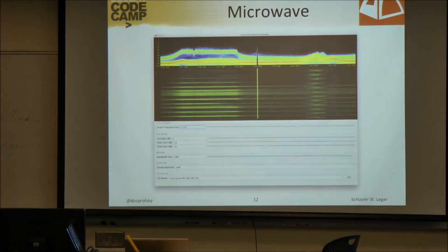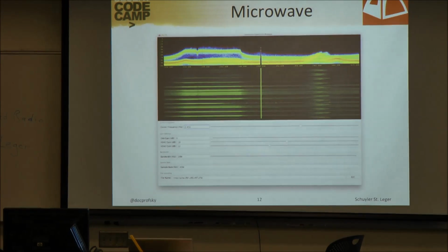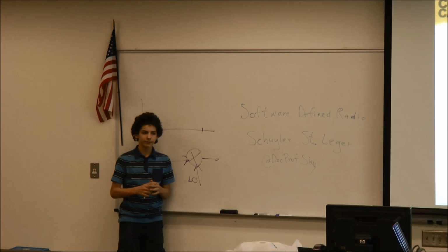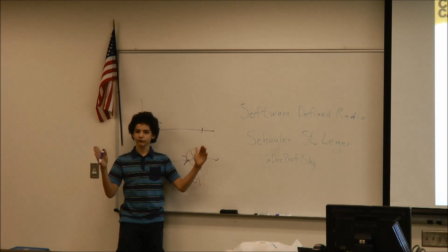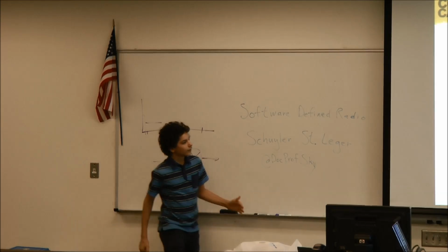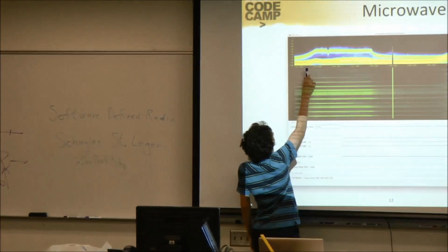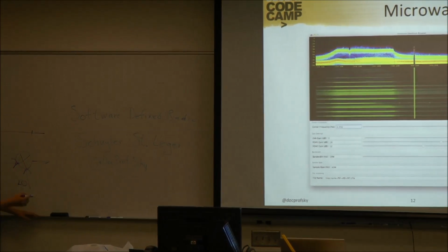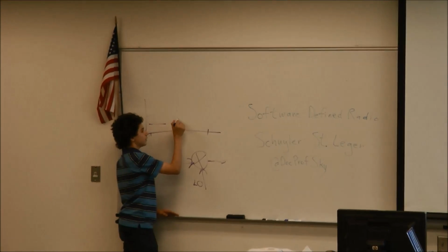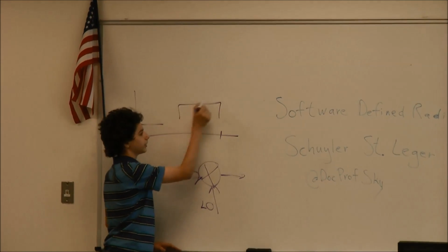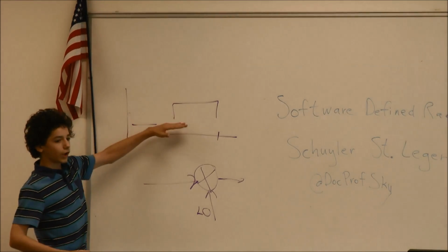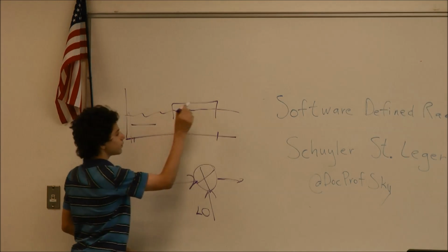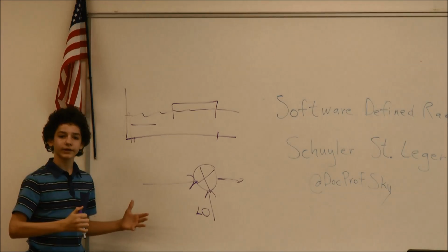First of all, if we go back to our spectrum here, the way Wi-Fi works is you're familiar with channel widths of 20 megahertz or 40 megahertz, right? So this width from about here to here is about 20 megahertz. And if we have our channel here that we're using, and let's say there's a faraway client, so this signal is here, and here's the noise. You can discern the signal, but you don't have that great strength.